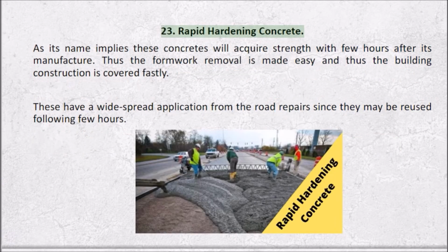23. Rapid hardening concrete. As its name implies, these concretes acquire strength within a few hours after manufacture. Thus formwork removal is made easy and building construction is completed faster. These have widespread application in road repairs, since the road may be reused after a few hours.